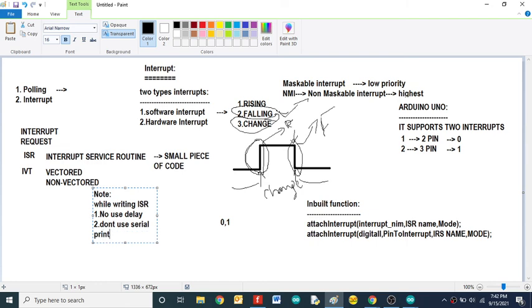Now I am showing a simple example. Okay. In a larger application, or if your application has more lines, we may see an effect on the operation. When you create the ISR with delays or by printing many serial prints, we will get inaccurate output.